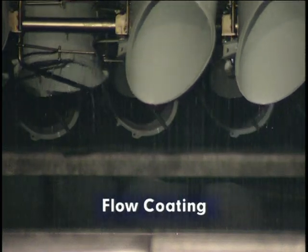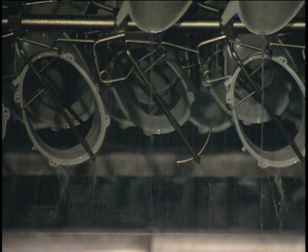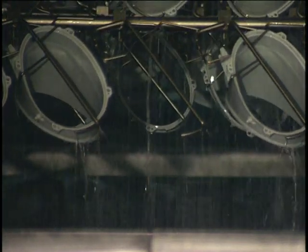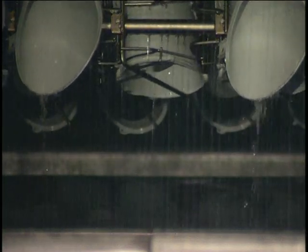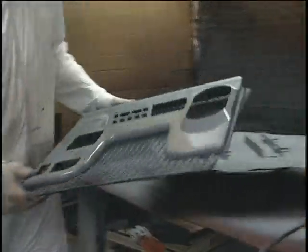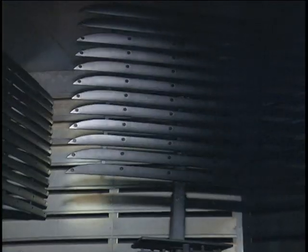In a flow coating system, a number of individual streams of paint are directed at the plastic part. Excess paint is collected as it drains off, where it is pumped through filters and recirculated for reuse. Once a paint coating has been applied, it is transformed into a finished solid paint film by curing. Depending on the coating, curing can occur at room temperature or within an oven.